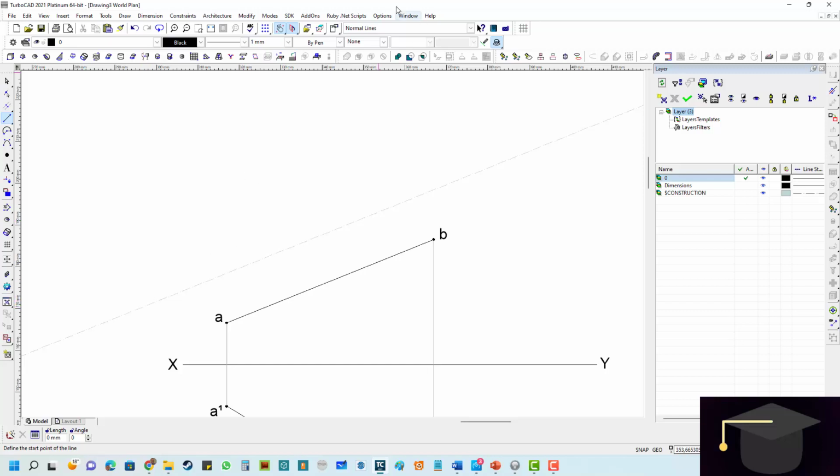On that line, I want to activate my snaps again. I'm going to start, and I'm going to change that value to 0. Then I'm going to drag on this new version, the 21 version, upwards on TurboCAD. It will snap to that angle of the line if you click and place it, and then I will stop it at that. It's not a definite length, it's just an estimated proportional length. So there I have my next XY line.